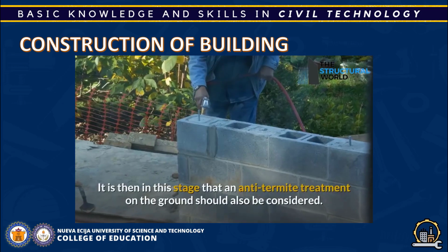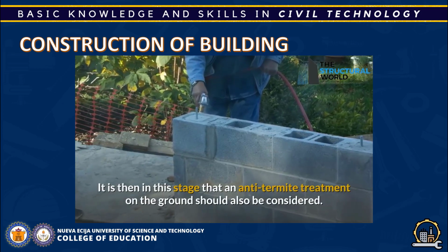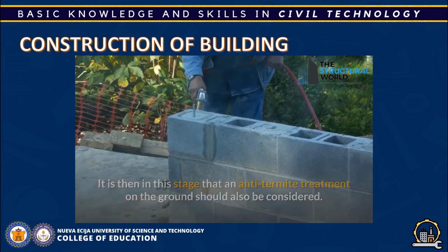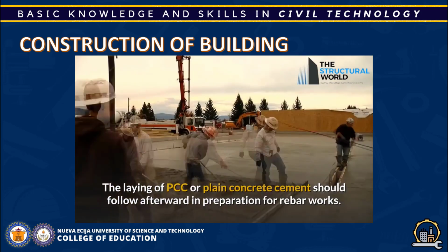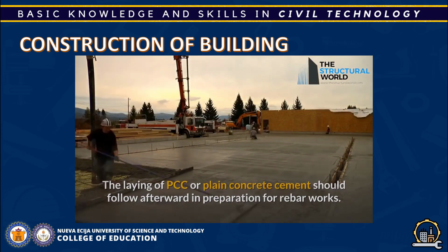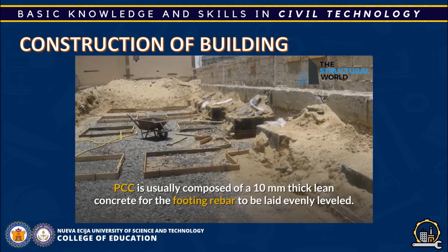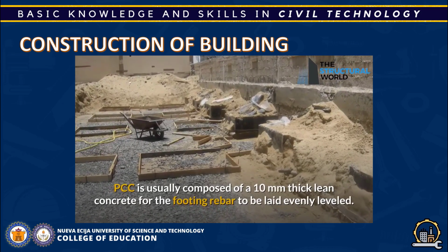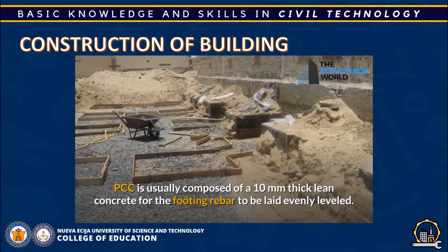It is then in this stage that an anti-termite treatment on the ground should also be considered. The laying of PCC or plain cement concrete should follow afterward in preparation for rebar works. PCC is usually composed of a 10 mm thick lean concrete for the footing rebar to be laid evenly leveled.